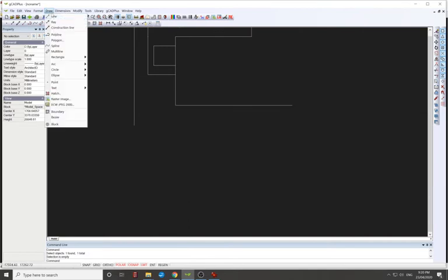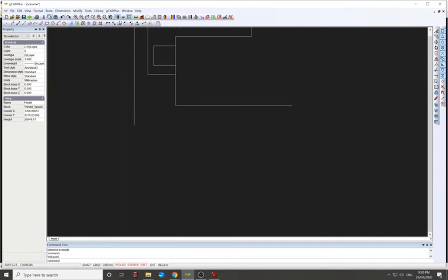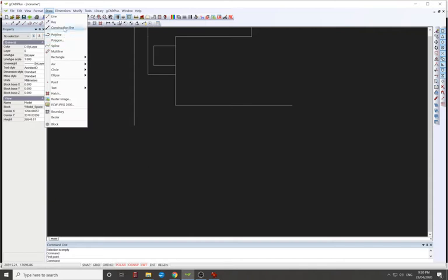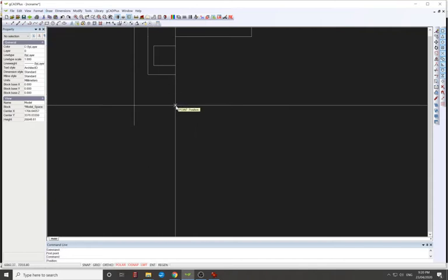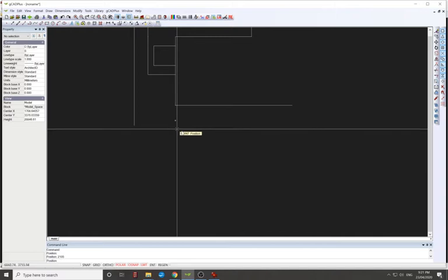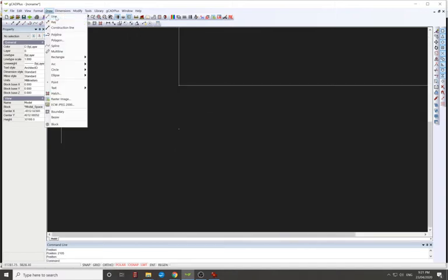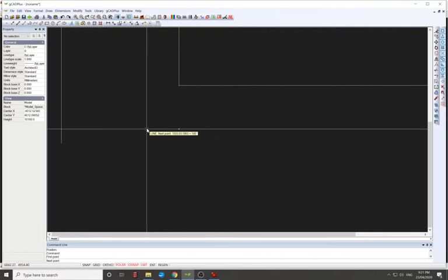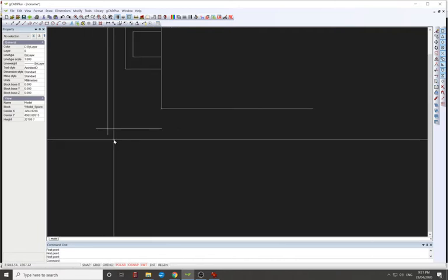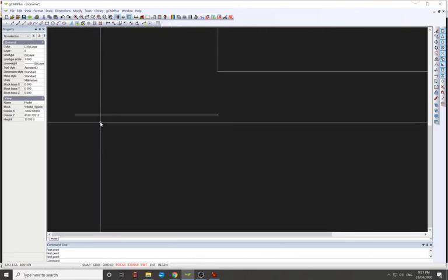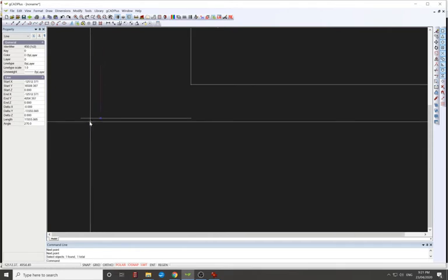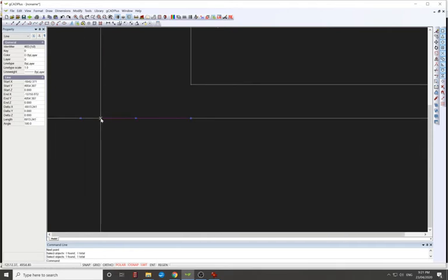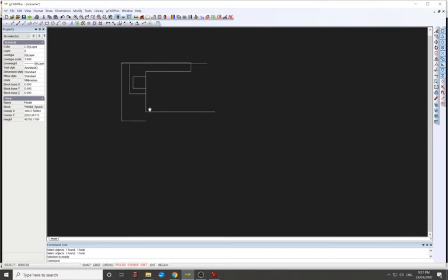So then with the other one here, we've got draw a line. So again, we'll use a point if you want to. Points there. So we start at the corner. We go out this way. Hold the tracking, 2105 to there. That's the boundary. Draw a line. Overrun it, and then rather than trim, it feels like you're doing extra work. I can just do 2 clicks like that. So I'm just, for the most part, doing that most of the time.